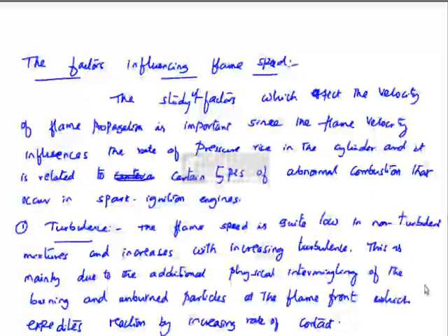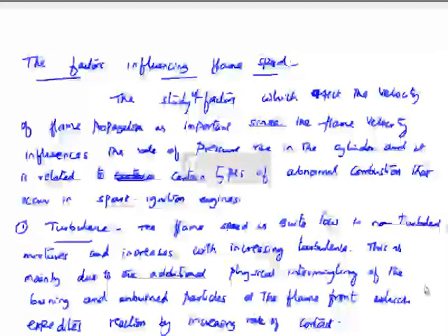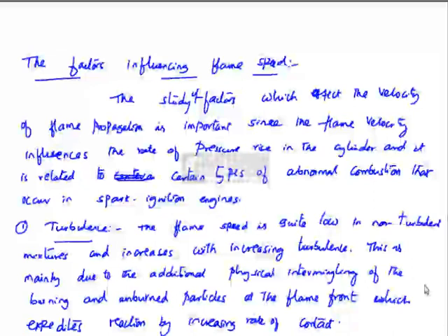The turbulence in the incoming mixture is generated during the admission of fuel air mixture through comparatively narrow sections of the intake pipe, valve openings, etc. in the suction stroke. So the turbulence is already generated, particularly during the admission when petrol vapor and air mixture is passing through the valve opening, intake pipe, etc.